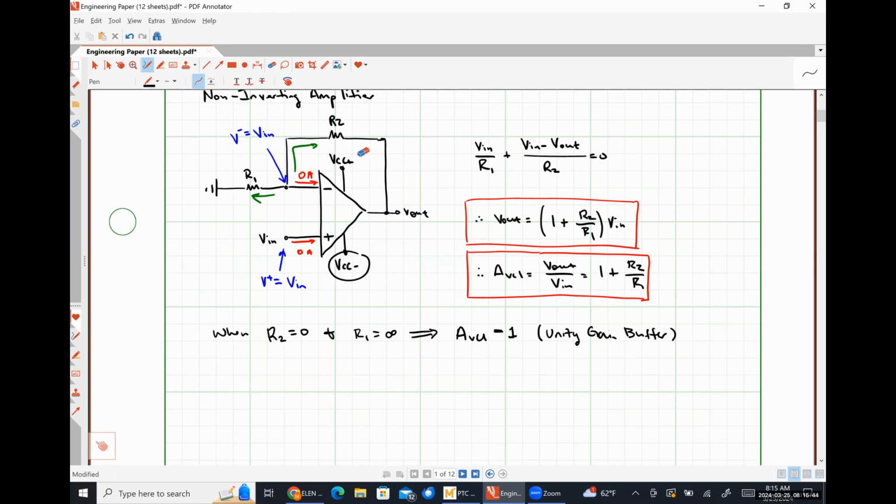Okay, so you might have a sensor that measures some amount of mechanical deformation. There's a special type of material called piezoelectric crystals that generate a voltage in response to mechanical deformation, right? So you can make all kinds of neat strain gauges out of them. Well, they're really good at making voltages, and they're absolutely terrible at producing a current. So we use a unity gain buffer to have a separate stage that allows later stages to pull current from the supply rails of the unity gain buffer, not the sensor itself.